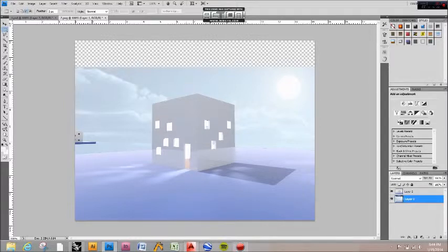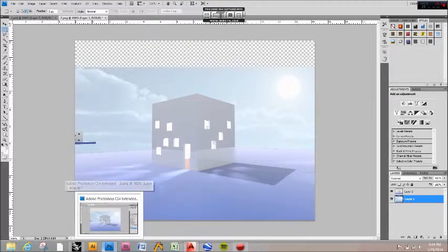So yeah, guys, have fun, tweak things. If you don't like how reflective this wall is, try the ceramic white porcelain that is not reflective. Just try over and over again until you get the right look. And tweak it in Photoshop as much as you want, but get the right look in Rhino and V-Ray from the start so that Photoshop will be minor touches, not really something that you need to spend too much time in.